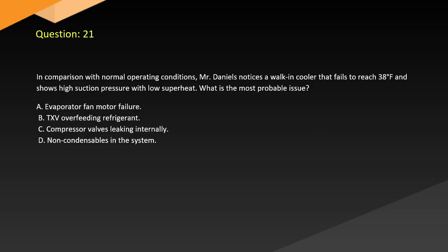Question 21. In comparison with normal operating conditions, Mr. Daniels notices a walk-in cooler that fails to reach 38 and shows high suction pressure with low superheat. What is the most probable issue? A. Evaporator fan motor failure. B. TXV overfeeding refrigerant. C. Compressor valves leaking internally. D. Non-condensables in the system.